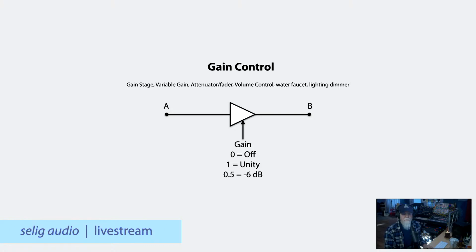Halfway down the knob may not be 6 dB because the knob would be scaled differently. So you wouldn't want the knob to be scaled linearly where 50% was in the middle. You want that number to be up higher because we don't hear linearly, we hear logarithmically, and it's confusing to explain, but you understand that when you